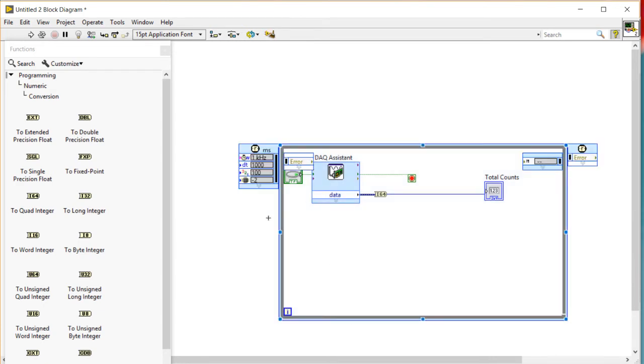And what it allows you to do is specify the period, or that is the time between the start of one iteration and the start of the next. So it precisely times the length of the entire loop, including the amount of time to check on the DAQ Assistant and do any math in here. And that whole time plus the delay is exactly 1000 milliseconds. So we know how long the loop took. And this is more precise than simply putting a delay in a while loop, which is what we need for our anemometer. One problem solved.